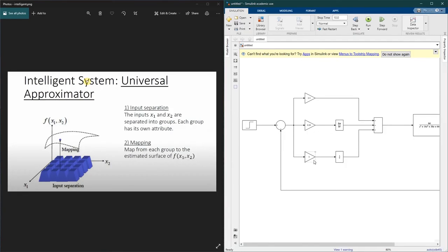So sometimes these two controls are used by combining them together, both fuzzy logic and PID. Then what will fuzzy logic be used for? It will just adjust the values of Kp and Kd all the time to make it a universal approximator, and use PID control, which is already stable, to control a system. Okay, this is all about the control system subject, and that would be it for intelligent control, which is usable and not complicated. The system can be created standalone on a microcontroller, preventing the need for an unnecessarily big processor.